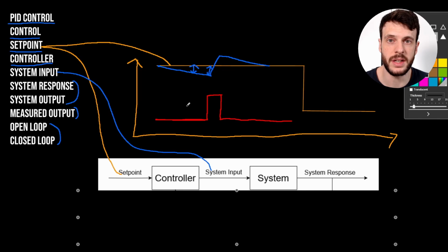Now you can imagine that that works a lot of the time, but over time it can go out of sync. The water temperature doesn't quite track where it thought it was going to be. So over a long period of time, the water will stop being the temperature it needs to be, and the open loop controller doesn't control it effectively. For some applications, that's fine. For a water tank, you want a closed loop system. You want to have some kind of feedback.